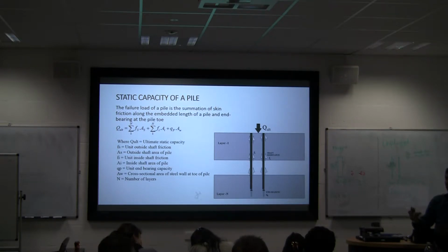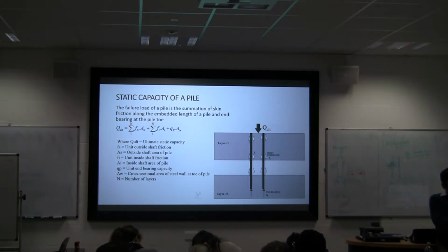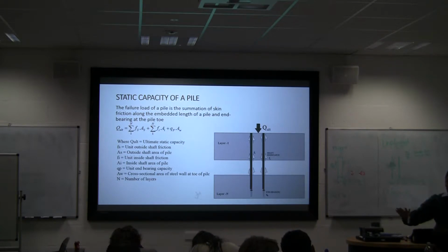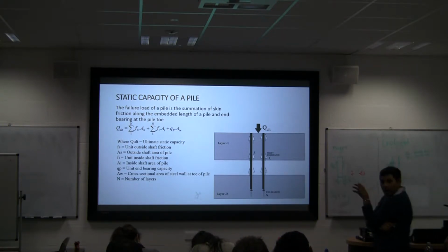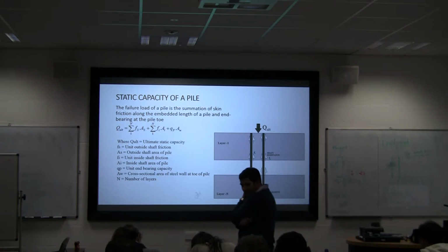Right? So when you drive the pile, because of the stress waves, you're banging a big hammer. So you're not letting it be like a plugged case. So it drives like unplugged. But once you finish the driving, it's stable, steady state, everything is normal. When you have the load, it acts like a plug. Right? It's quite complex in a way how you do it, but in practice it's easy.